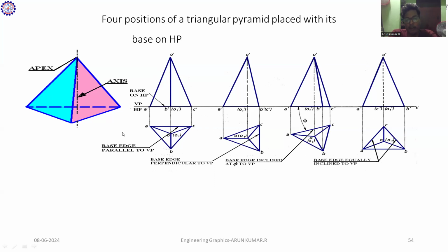Now proceed to the front view. To construct the front view of the given solid, draw horizontal lines from each corner: A comes under A dash, C under C dash, B under B dash, and similarly O goes to O dash. It has a certain height, such as 50 mm, 60 mm or 70 mm, whatever is mentioned.